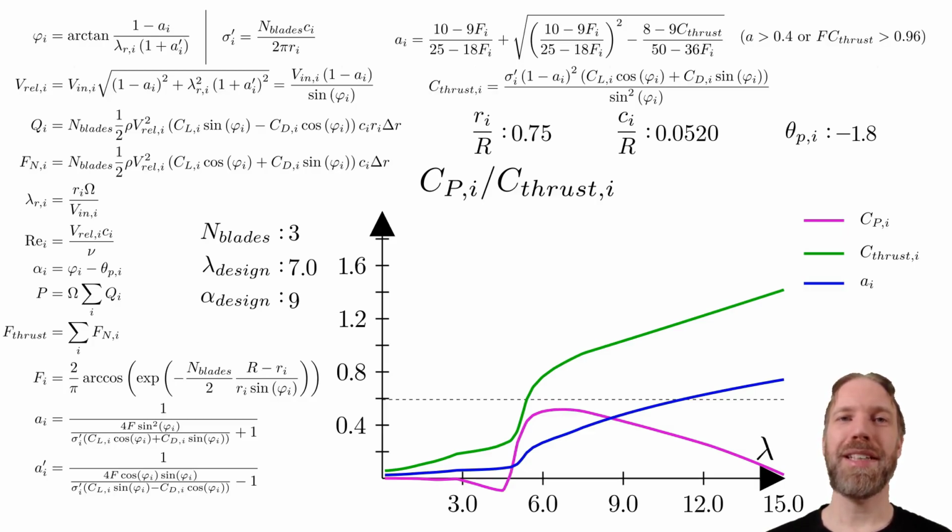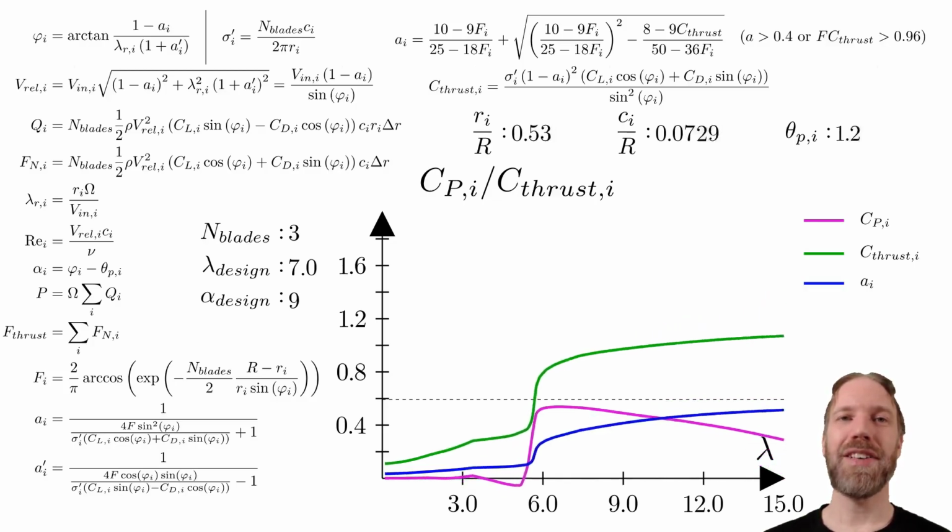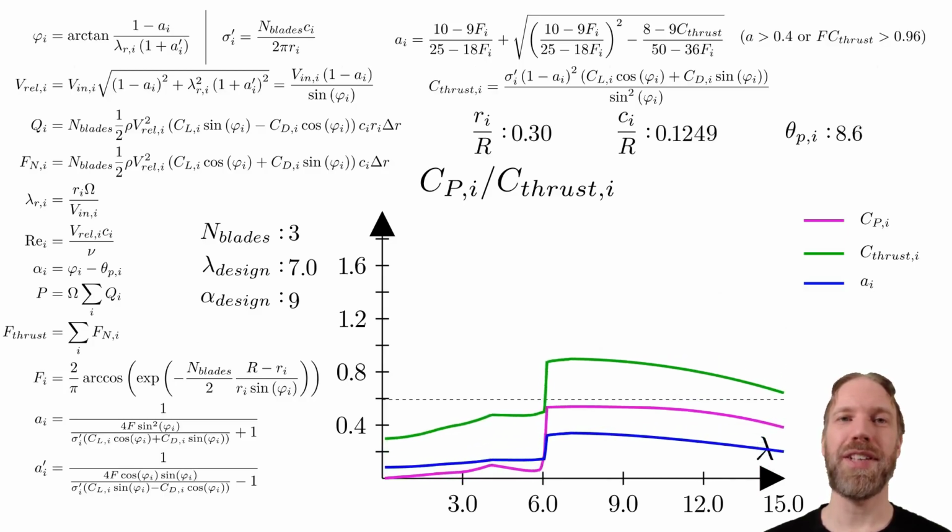Let us look at the position closer to the turbine center. Now we can basically see a jump in the power coefficient at tip speed ratio 6. The short explanation is that the blades stalled at tip speed ratio below 6. To explain the jump, we need to remember that the blade element model is a steady state model. When the blade stalls, the actual induction factor decreases. This pushes the blade deeper into stall, which causes the jump.